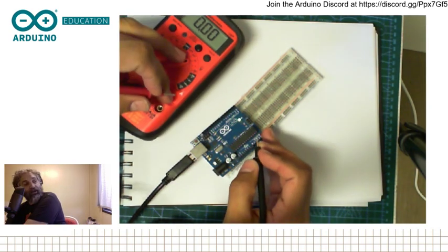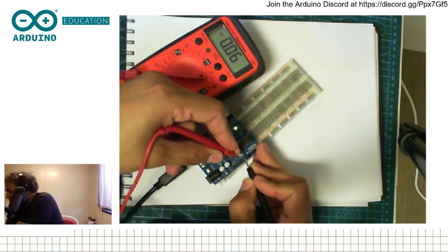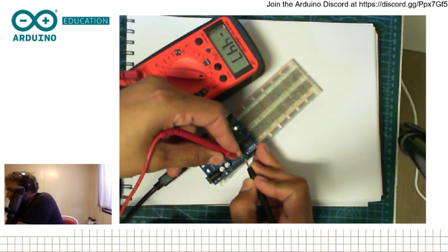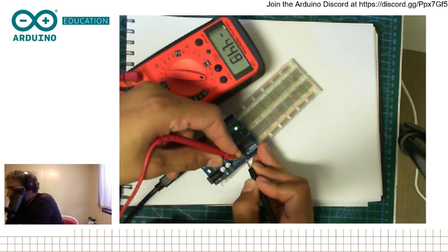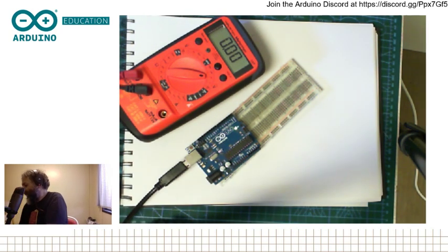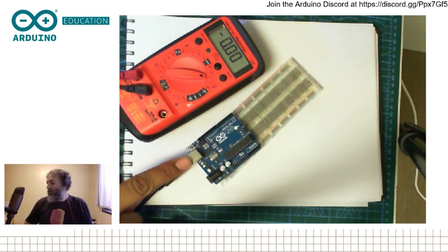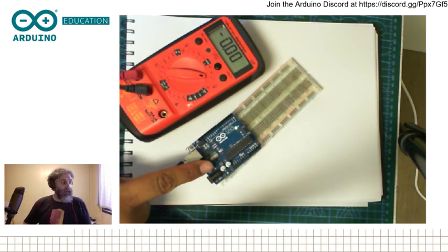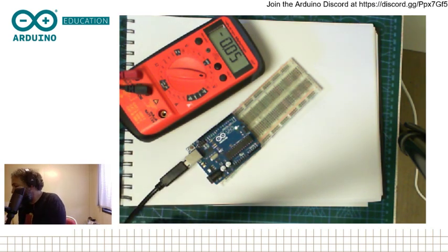So I guess you can read that properly. If I touch on the ground pin and I touch on the 5 volts pin, you see how right now it's giving me a measurement of 4.48. And that is more or less 5 volts. I mean, it's not exactly 5 volts because I'm getting 5 volts through the USB port, and there are some components on the way that are draining some current, and so on my 5 volts pin, I'm not getting exactly 5 volts.